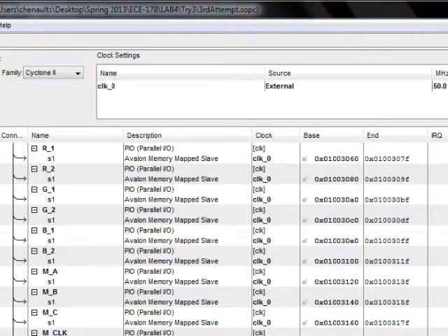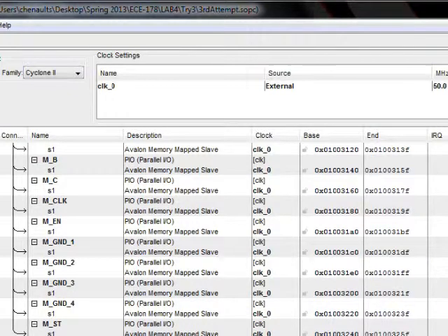And then here we have R1, R2, G1. These are all GPIO pins that are actually mapped on our board. We use this naming convention to help us out later when we write the code, so we can address them specifically instead of saying GPIO 1, GPIO 0, etc. Here we also see the M_clock, which is a very important pin that controls a lot on the LED matrix. That pin is going to give us all the clock edges that essentially make the LEDs light up and align all the timing for our LED matrix.